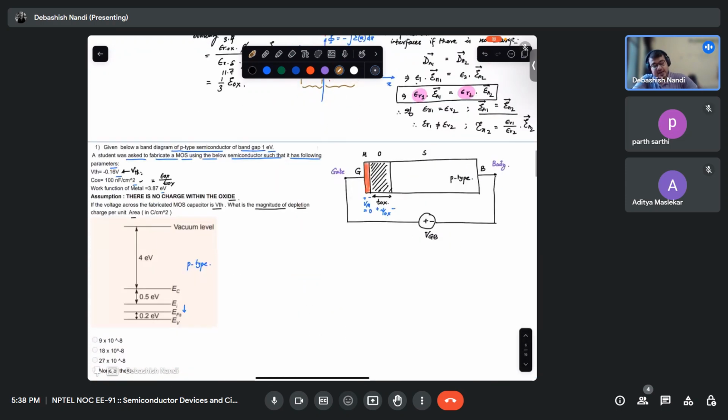See, what happens is that as soon as you apply a positive voltage with respect to this, there will be some positive charges on the gate. Okay, what it will try to do? It will try to attract negative charges from deep in the P type semiconductor towards this surface. Why can't the charge be present inside the insulator? Because there is no free charge inside the insulator, right?